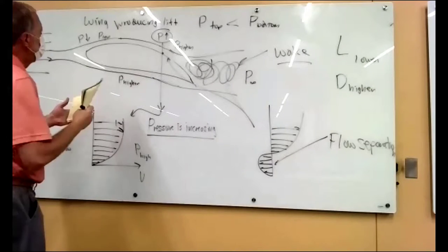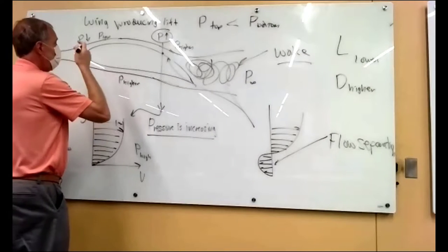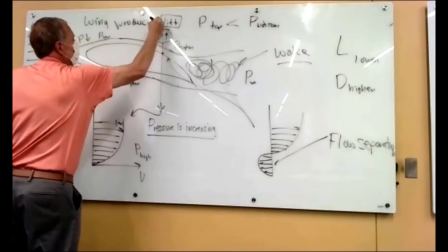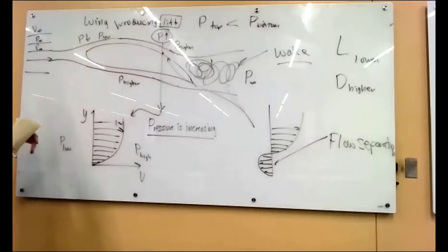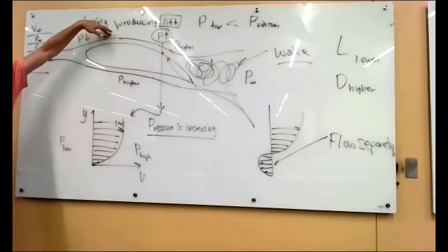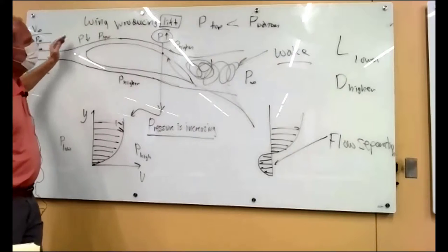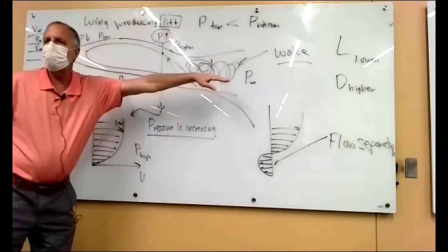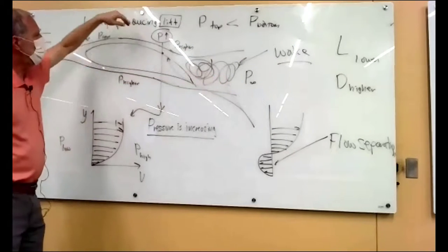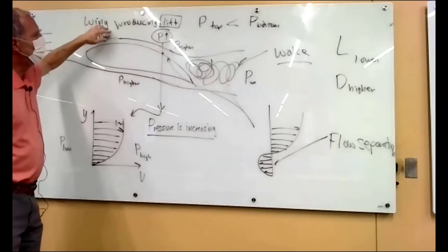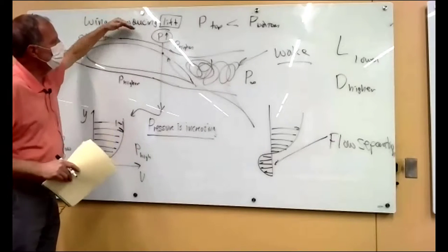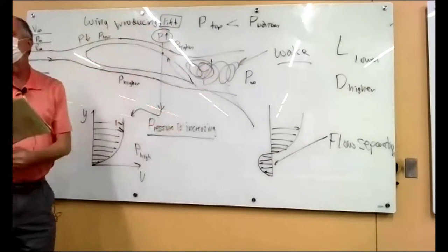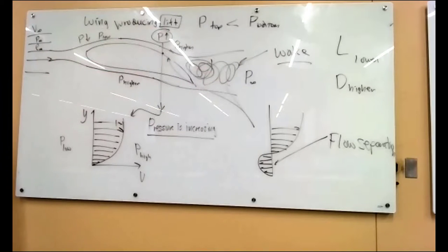And if you're at a really high lift situation, right, we're generating lift, that means the pressure is really low, and so it has to go a lot more into the higher pressure region. So the lower the pressure is to start out, the more time the boundary layer spends in that pressure recovery region, and the more separation you get. Yeah?